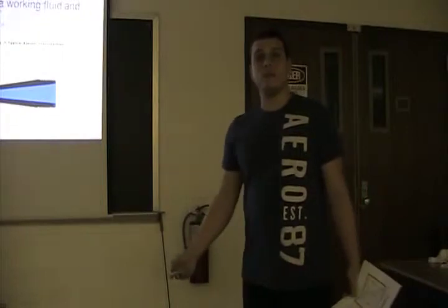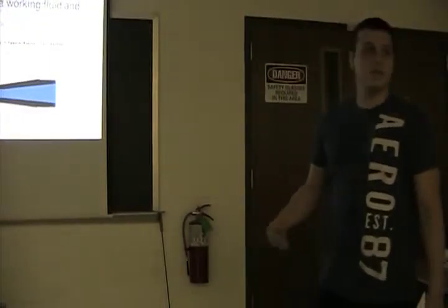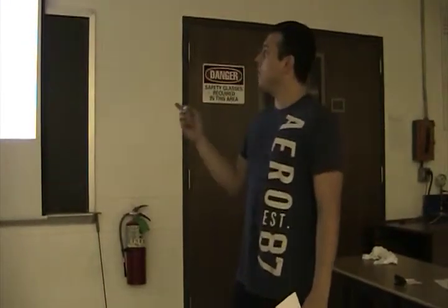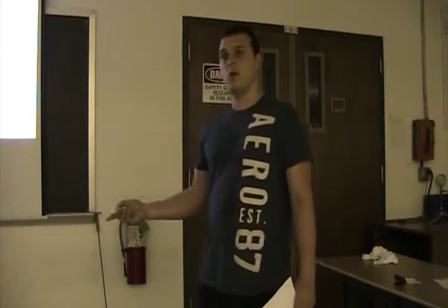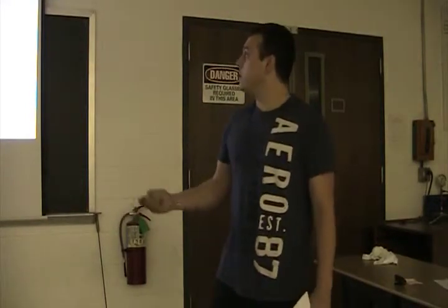First of all, what is a steam ejector? A steam ejector is a converging diverging nozzle that entrains a secondary fluid. Basically, it utilizes a working fluid and the Venturi effect to pump a fluid from a lower pressure to a higher pressure.